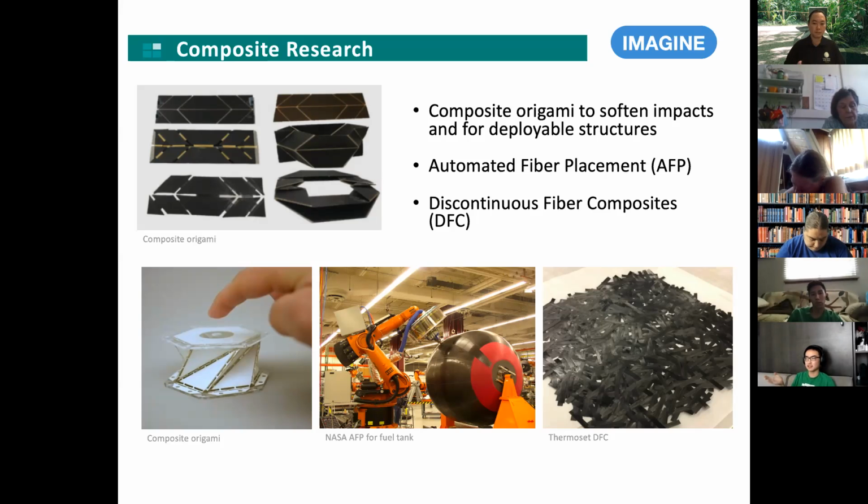Another thing for origami composites is deployable structures. For aerospace applications, you can send up something lightweight like carbon fiber, folded, so it saves a ton of volume that they can fill with other stuff. Once it's in space, it can unfold to the shape they want. And in space, they're now developing UV cured resins, so it'll just cure on its own from the sun.